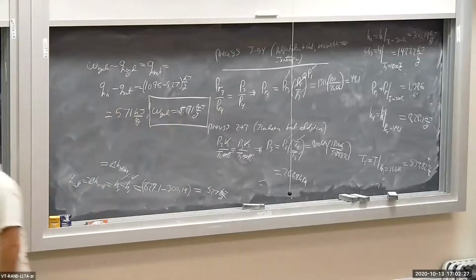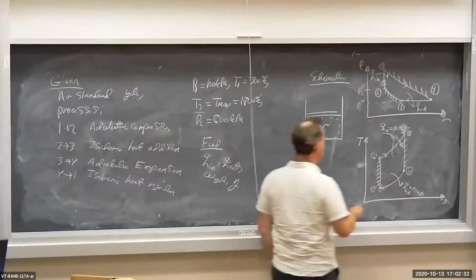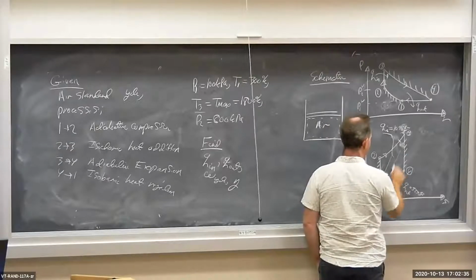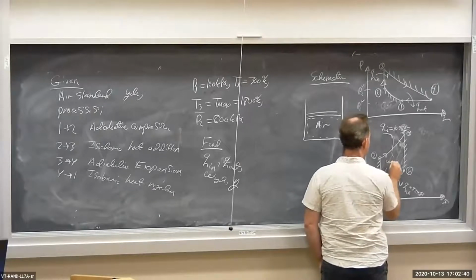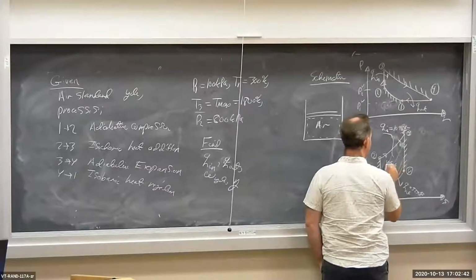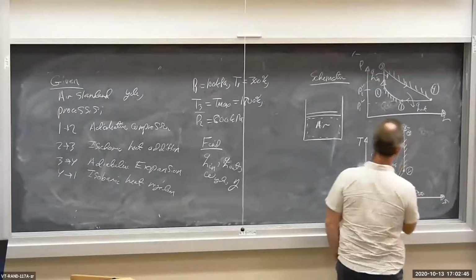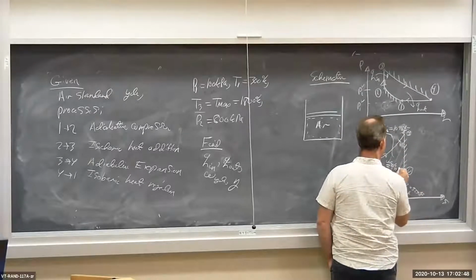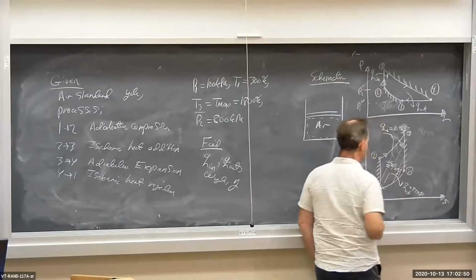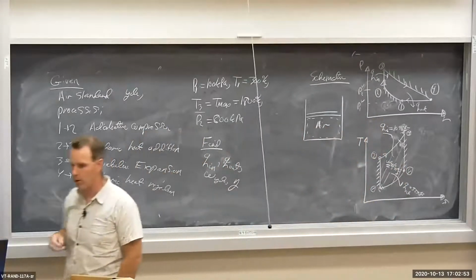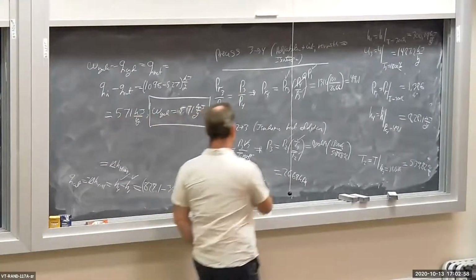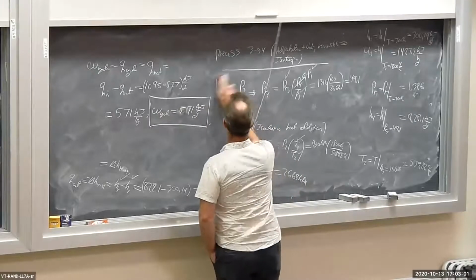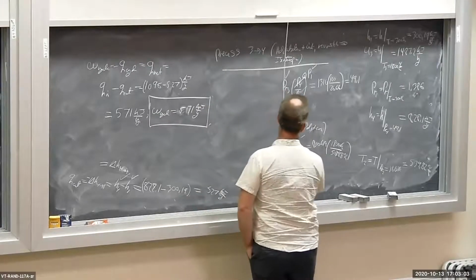571, okay? So let's put this on the TS diagram. The net work is the area bound by the TS curve. So I get W cycle is equal to 571 kilojoules per kilogram. Okay, that's the specific work for the cycle. Let's calculate the efficiency, eta, for this cycle.